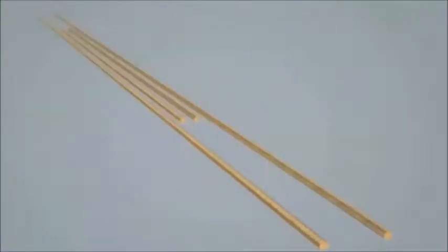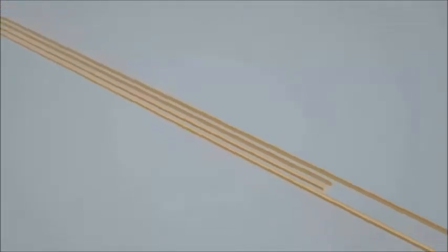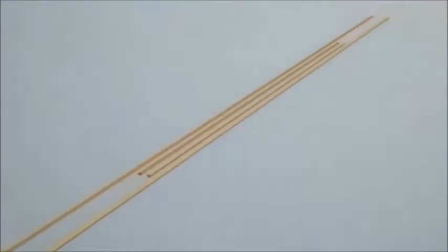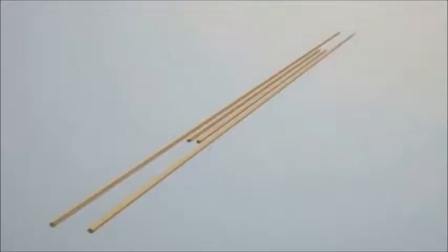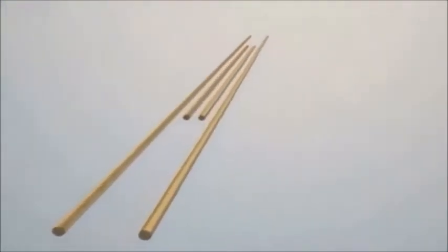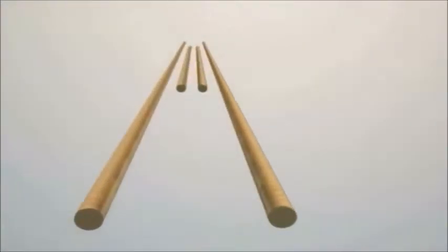Here, we can see the animation of the ground beam and how it is being constructed, starting with the steel bar. This animation shows the steel bar being arranged properly from the bottom. The bottom will have 2 long steel bars and 2 short steel bars, with the same diameter of steel used.